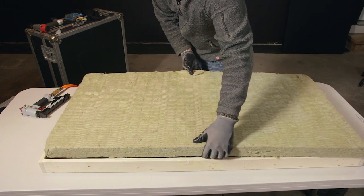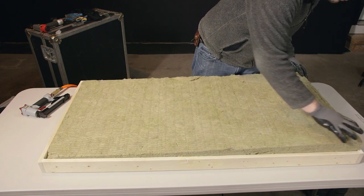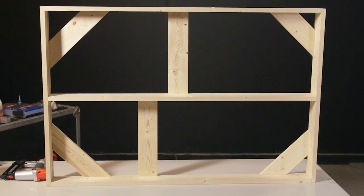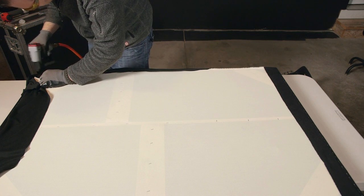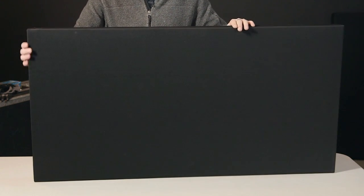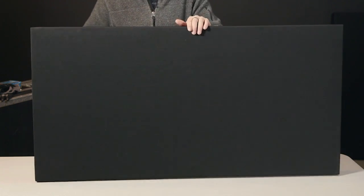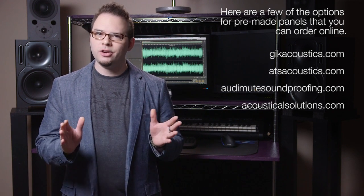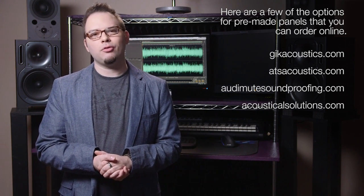2-foot by 4-foot rigid mineral wool and fiberglass boards are the two most common types of materials used for commercial sound absorption panels. Most of these products are frames made out of wood or metal that go around the outside of these boards. The frame provides a place to attach hardware for wall mounting, and then these panels are wrapped in fabric for a nice finished look. These panels are quite easy to make, and you can check out a few tutorials that I created on photo.tutsplus.com for more information on how to make your own. The panels can be made for a fraction of the price of commercial panels, but I understand that the DIY solution is not for everyone.